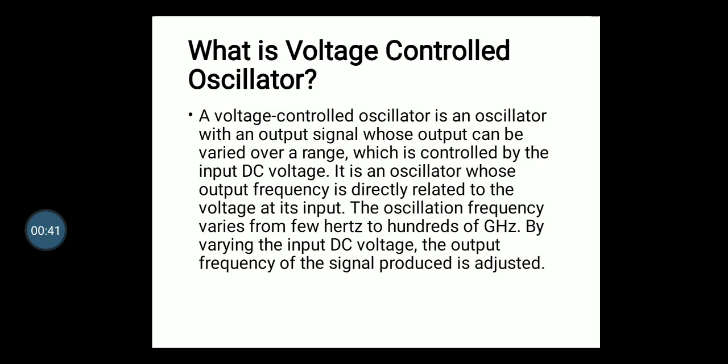The voltage controlled oscillator is an oscillator whose oscillating frequency varies in response to a control voltage VC. A common type of VCO available in IC form is Signetics NE or SE566. The pin configuration and the block diagram are shown in the figure, referring to the timing capacitor CT.